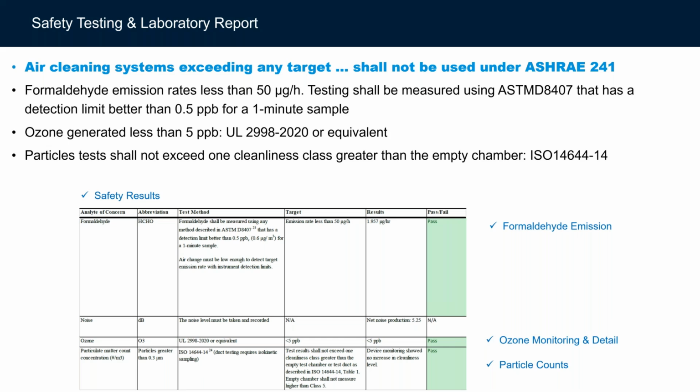That's the particulate count. And so that's how you can understand reading these safety tests. I think you can agree with me, it's really stringent. It should give you a lot of confidence when you see these reports and then go to recommend or design around a particular electronic air cleaner, that you're adding a really effective solution that is extremely safe.